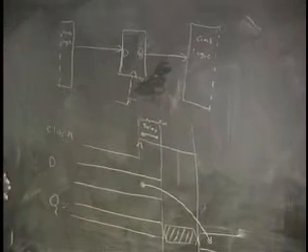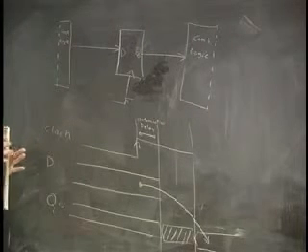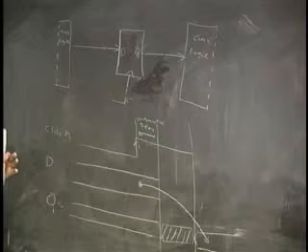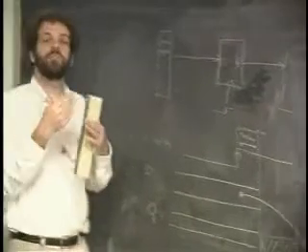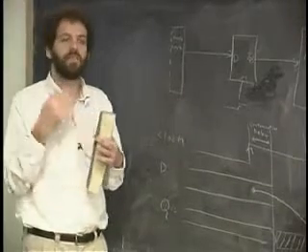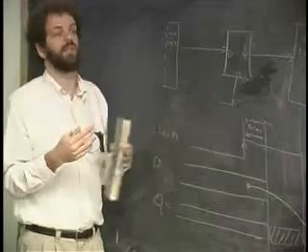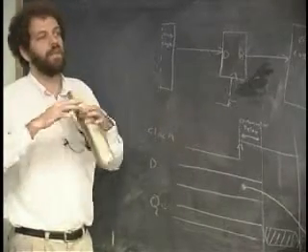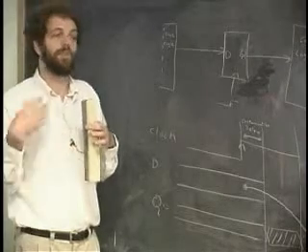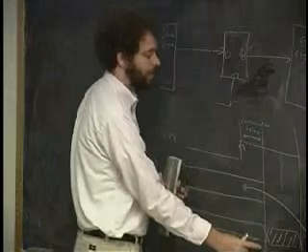And what we're going to talk about for the rest of the class today are the specifics of the timing of how these pictures are taken. The shutter is snapped. For a short time after the shutter is snapped, the old image is still there. It takes time for the logic inside of here to say, oh my God, the clock went off. Okay? A short time after the clock goes off, it says, okay, I've got to change the picture from the old picture to the new picture. So that time is called the contamination delay.